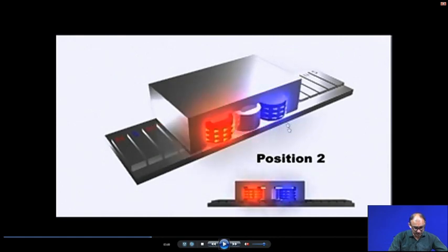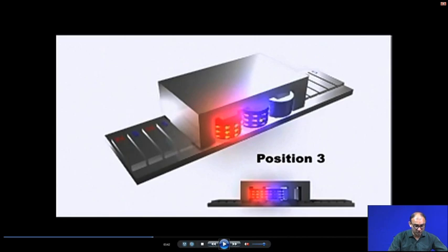Now, you can see that there is a switching over between the two. Now the middle one is off, and this one becomes negative or positive depending on these polarities. Now it has moved to the second position, and now it is in the third position. It depends on how frequently you are changing the position of the poles. The faster you change this, the faster you can get the movement in the linear direction.